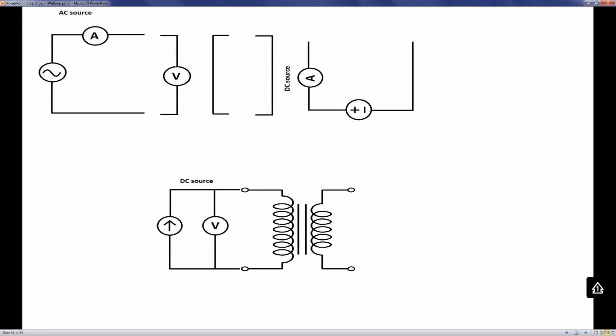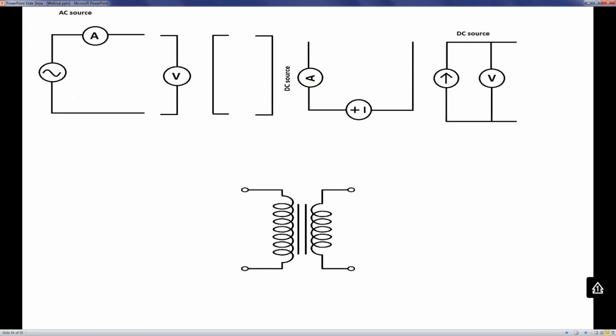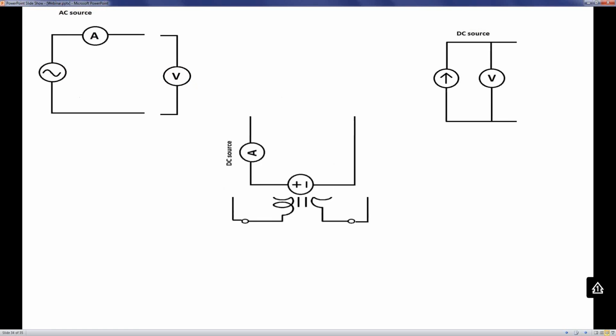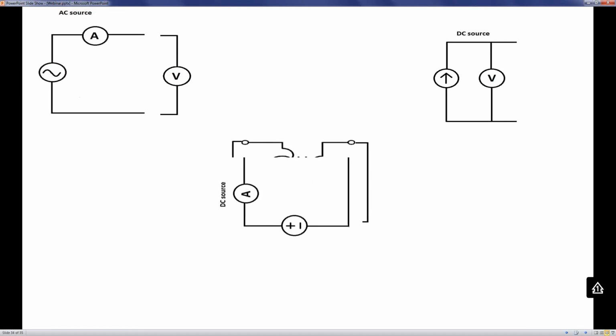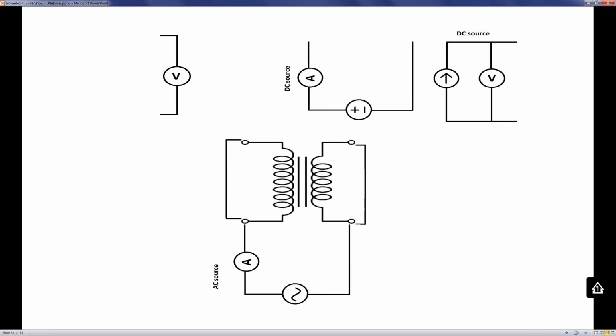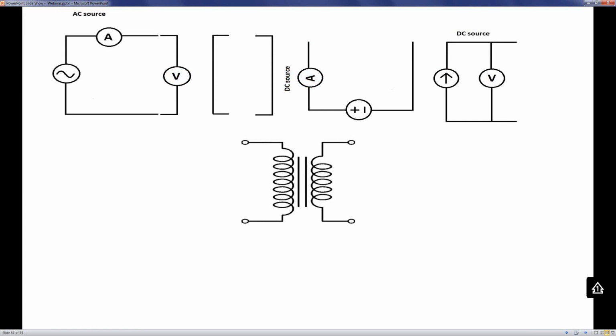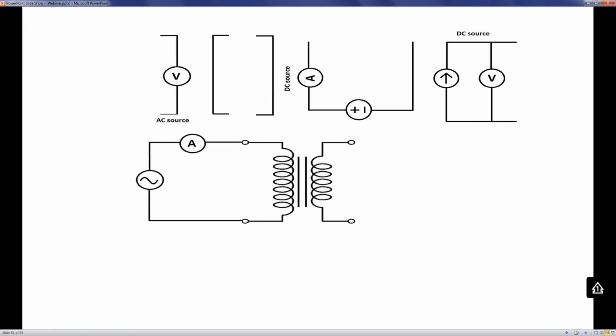So I would short the bushings of the windings. Then I would connect an insulation resistance test set to it. Once I'm done with the insulation resistance, I switch over to a power factor test set, do the power factor test, and then take off the shortings on the bushings. Then do the excitation current test. And once I'm done with that, I'll short the secondary winding and do the leakage reactance test.